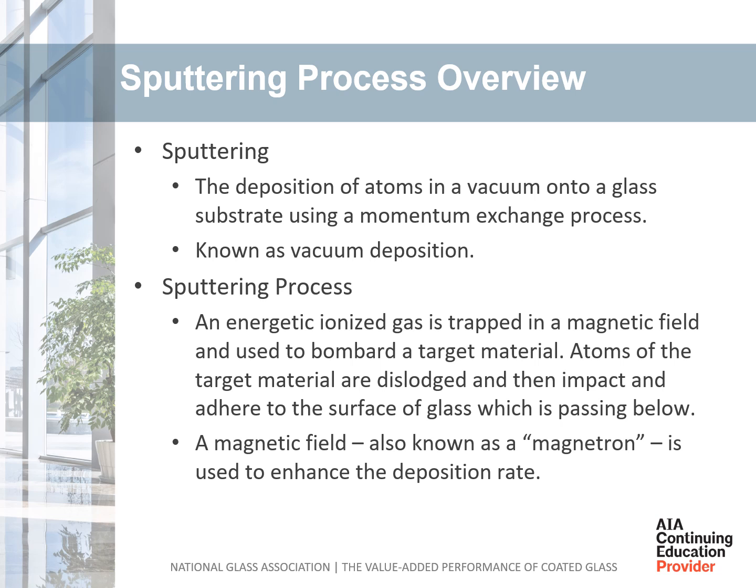Sputtering is the other major coating technology, sometimes referred to as soft coat. Sputtering is a process whereby an ionized gas molecule is accelerated towards a metallic or semiconductor target material under high vacuum. The momentum of the gas molecule dislodges a target atom, which is transferred to the glass surface. The material being sputtered builds up atomic layer by atomic layer, and a magnetic field is created to drive the ionized gas toward the target, which is the name of the process itself, magnetron sputtering.